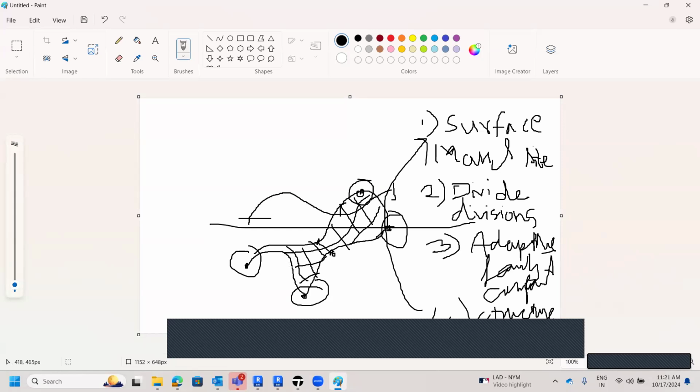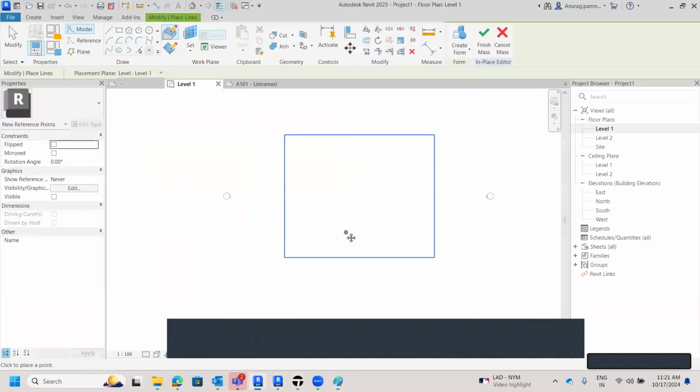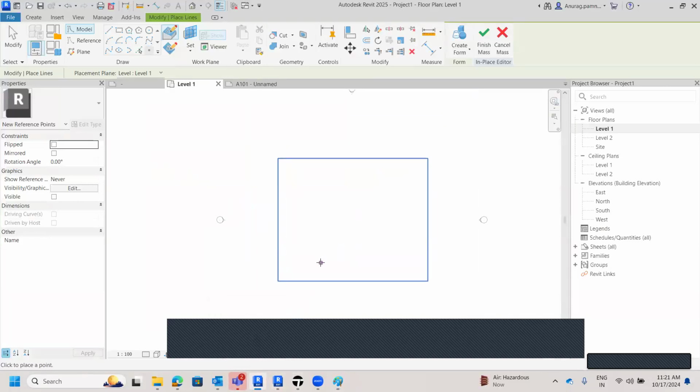But if you need to make it more precise, then suppose I also take one of the points over here to give it a height. So this would be one over here to give it the depth, and one again over here to give it the height. So in total, I should have 9 points to prepare this particular surface accordingly, right? So I would be going back onto the Revit interface, and I have to place 9 different points over here. So one,